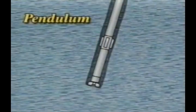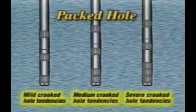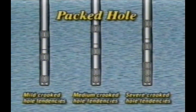The pendulum assembly employs a stabilizer up above the bit to center the drill collars and prop them away from the hole. This increases the straightening force and acts to reduce hole angle. The packed hole assembly, shown here in several variations, consists of large diameter drill collars, which impart stiffness, and multiple stabilizers, which guide the bit straight ahead. When properly designed for the formation, it can be quite effective at maintaining a constant hole angle.